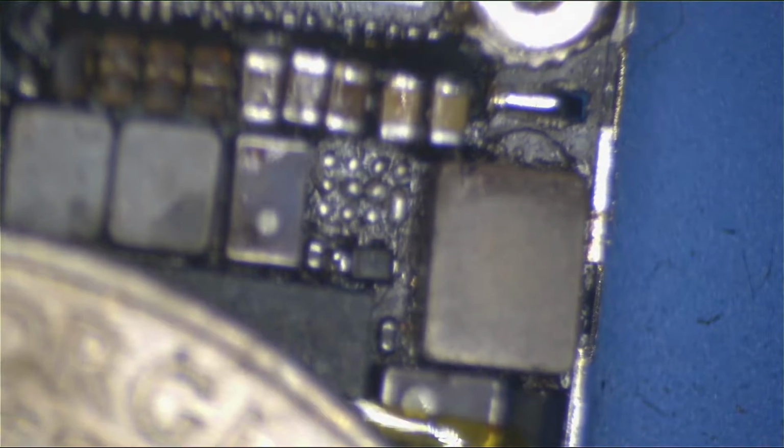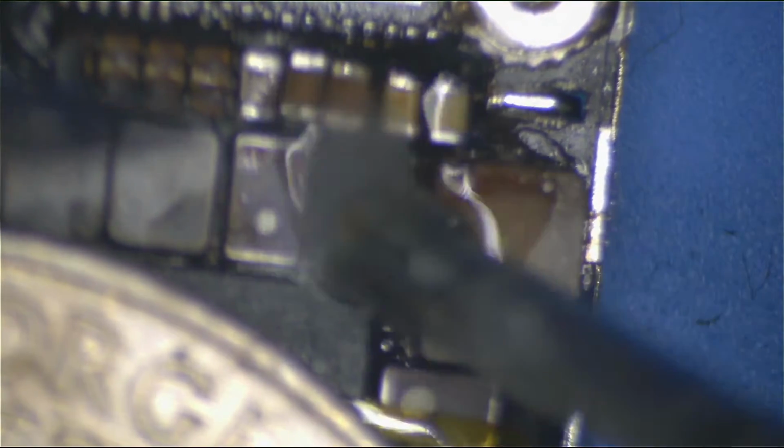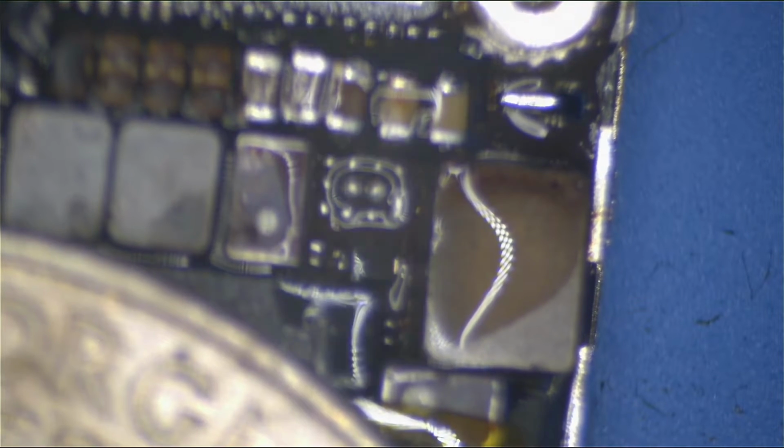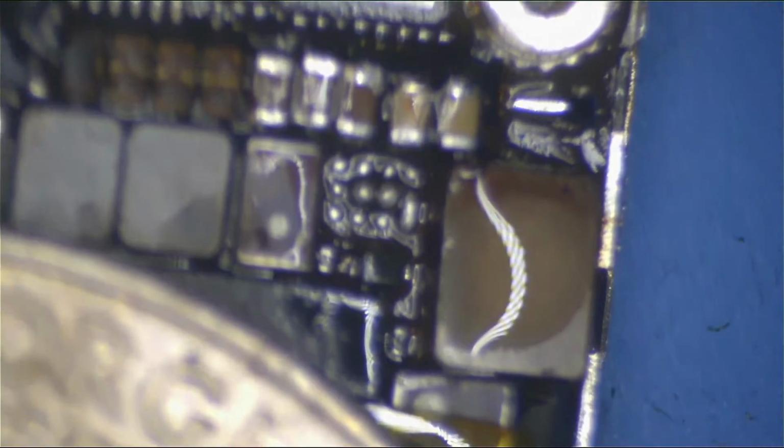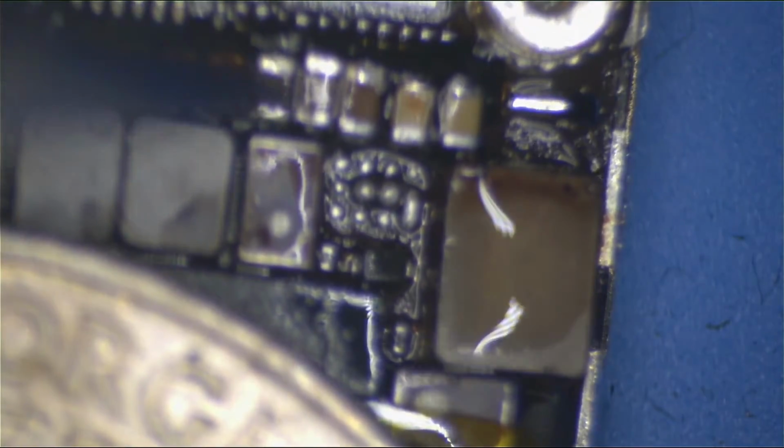So yeah, now we're really going to make sure, because two in a row have failed. There's obviously something underneath the VGA IC that's got to go. So now I'm going to really make sure those pads are flat, without wicking. I know it's just because I'm on camera that this doesn't work. I know that I can get away with not wicking these pads, and it's going to happen. I promise you.